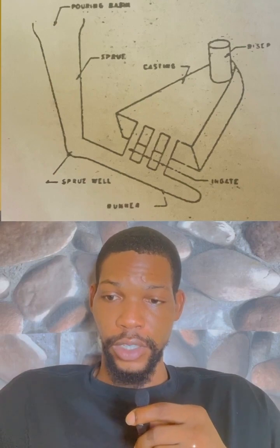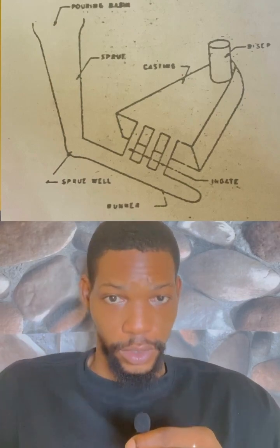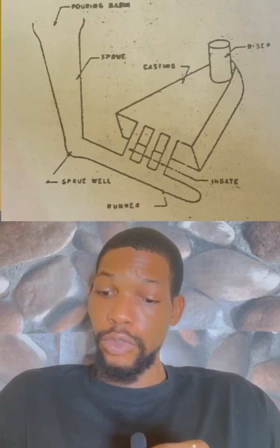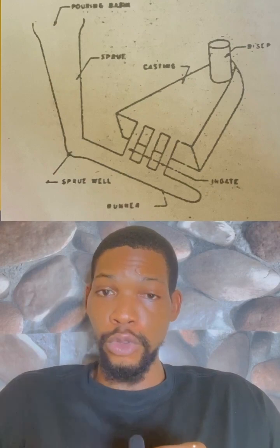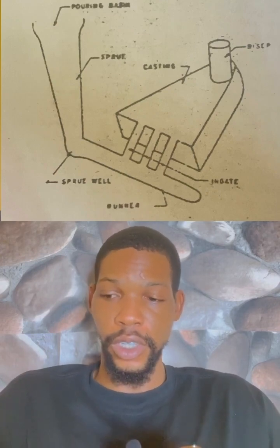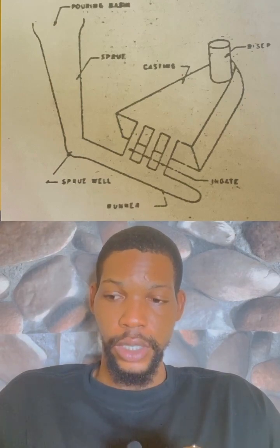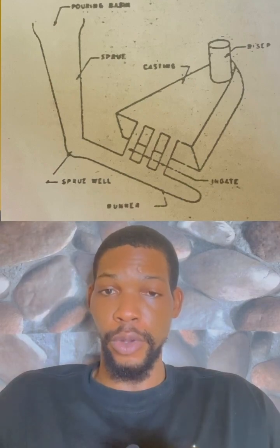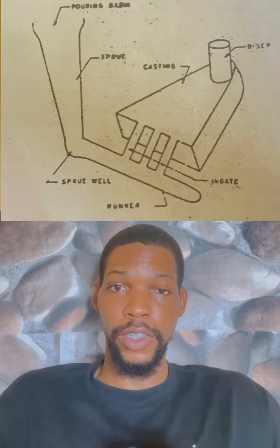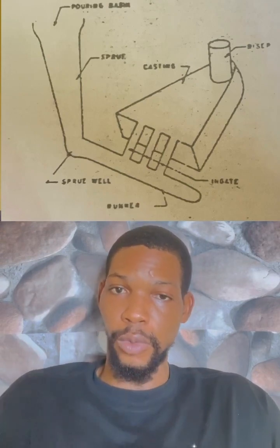The sprue. The pouring basin is just made to collect the pressure of the molten metal first. So instead of pouring directly on top of the cavity, which would wash away the mold walls, you apply your gating system, which starts from your pouring basin. The pouring basin comes in a funnel shape. It collects the pressure from the pouring of your melted metal. This is the benefit of it: it collects the pressure, reduces the turbulence, and reduces molten metal wall wash.